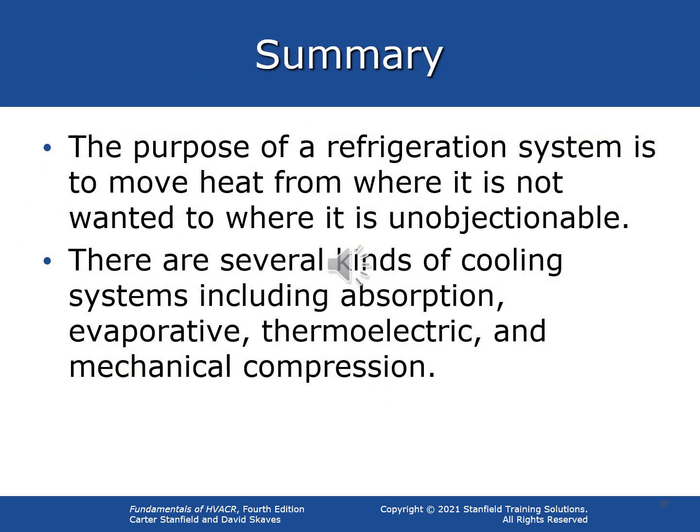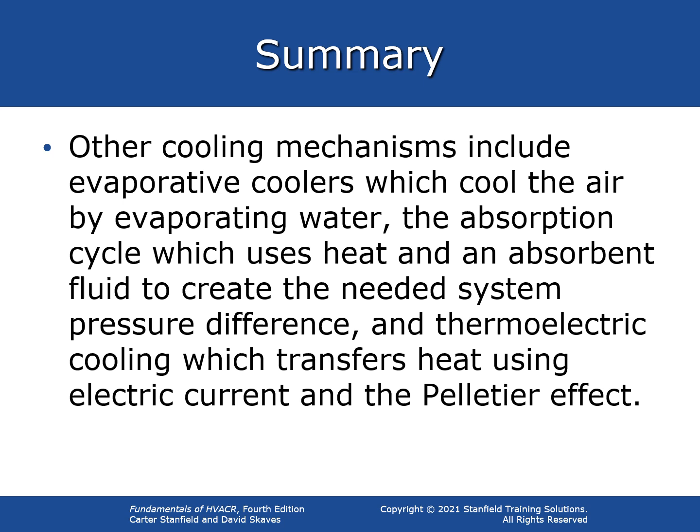The purpose of a refrigeration system is to move heat from where it is not wanted to where it is unobjectionable. There are several kinds of cooling systems, including absorption, evaporative, thermoelectric, and mechanical compression. Other cooling mechanisms include evaporative coolers, which cool the air by evaporating water, the absorption cycle, which uses heat and an absorbent fluid to create the needed system pressure difference, and thermoelectric cooling, which transfers heat using electric current and the Peltier effect.